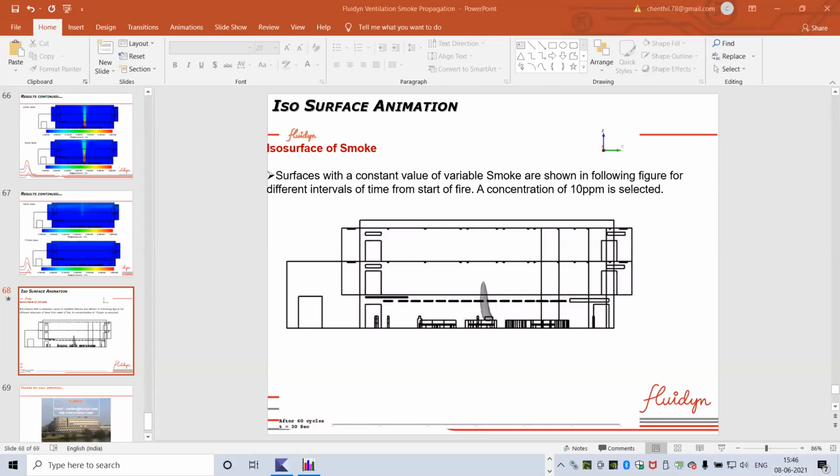I think in one of the talks scheduled tomorrow, he is going to give details of how it is done. So we actually solve a separate set of equations for the dispersed phase, and it will have components for Brownian motion, effects of gravity settling, and a few other things.